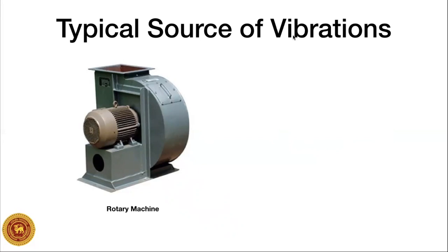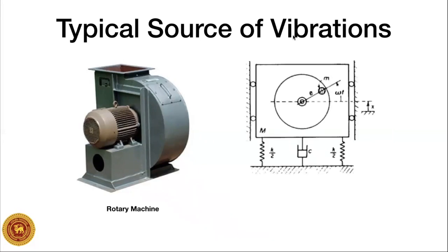Anything that has a rotating part, we would notice that there is a hum or a vibration that you would be feeling. If you try to understand this from a very simple point of view, this foundation can be thought of as being on 2 springs, and the structural damping of the foundation can be thought of as a shock absorber or a damper.